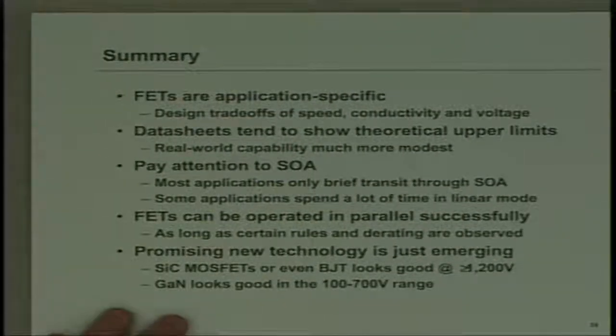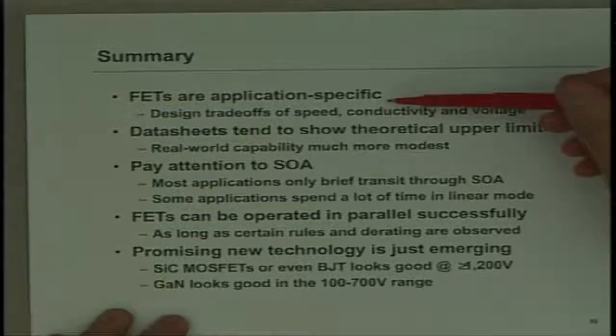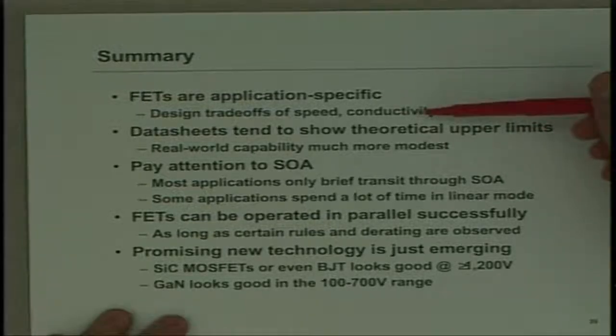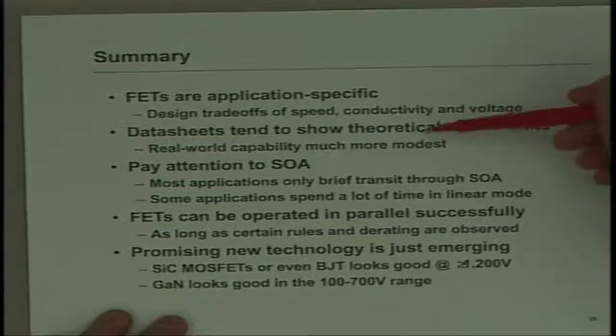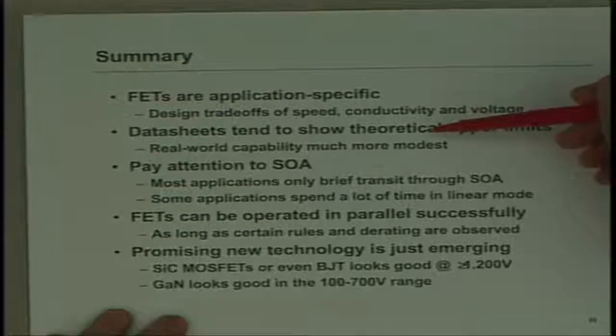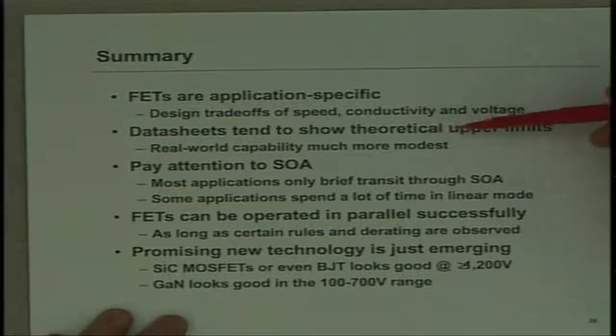So to summarize, FETs are application specific. Again, just like with the IGBTs, there are trade-offs in speed and conductivity and breakdown voltage. The data sheets tend to show you the idealized theoretical upper limits, so don't always believe those numbers are actually achievable. Real world capability is somewhere in the middle.